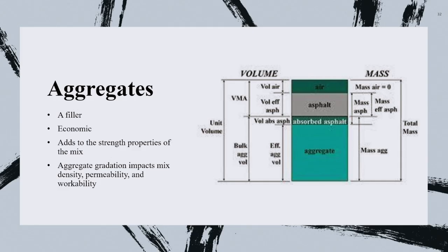Then you've got 7-8% of voids. Maybe you can have some admixtures, maybe steel fibers, but that's a fraction of a percent. But this block diagram for concrete is cement, water, coarse aggregate, fine aggregate, and air voids. And you have to proportion this so that volumetrically they add to 1 unit volume. In the US, we call it 1 cubic yard. Here in Nigeria, we call it 1 cubic meter, right? This is how you claim victory when it comes to the design of a reinforced concrete mix.